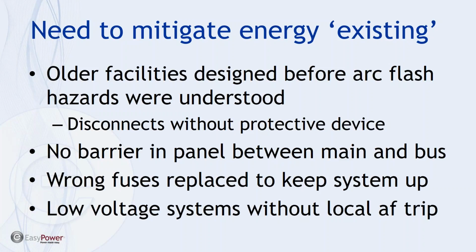And again, that's because the faster, quicker acting protective devices were placed in the medium voltage sections, and we may have low fault currents that take exceedingly long times to trip protective devices for disconnects, creating very hazardous incident energy, and that's what you can actually see. These situations come up when you do a study.